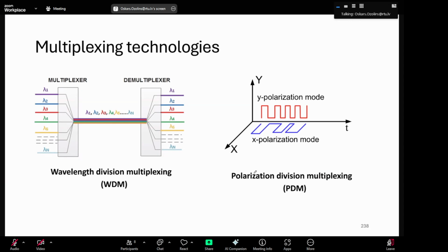Then what you can do more is that you can have multiple of these lasers, multiplexed and demultiplexed in wavelength division multiplexing systems. And in coherent communications, a big development was amplification in specific bands, because currently C plus L band is actively used for longer reach systems, with quite a high number of bits per symbol.